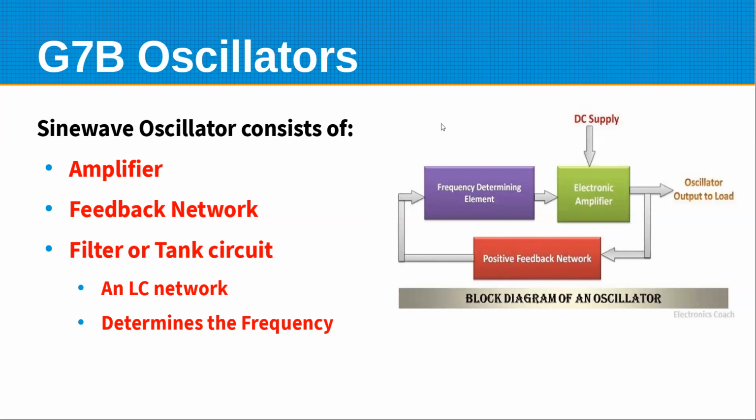And the key thing, it turns out, is the feedback from the amplifier has to have an overall gain of 1 in order for it to sustain oscillation. Now, it may take a gain of higher than 1 to get it started, but in order for it to continue oscillating, the feedback has to be just enough to offset the losses. So the gain is 1 around the loop.